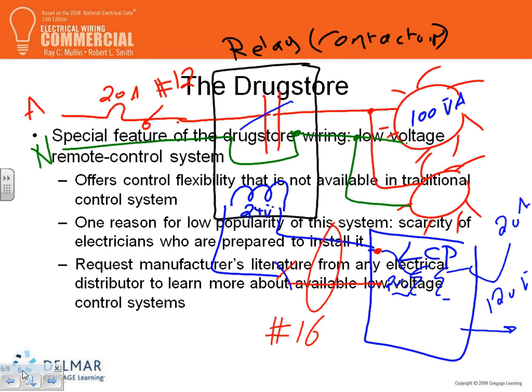You turn it, you energize this coil, and it shuts. Or you can grab the whole wiring in here, and have a contact controlled by another relay that receives a signal from China through the internet and closes an electronic contact to energize this coil to turn the light on and off. Or a timer. Yes, sir. Well, I was always under the impression you wouldn't want a snap switch on that. The whole purpose of a lighting control panel is so that it's automatic. Absolutely. You can have an override though. You can override these, sure.